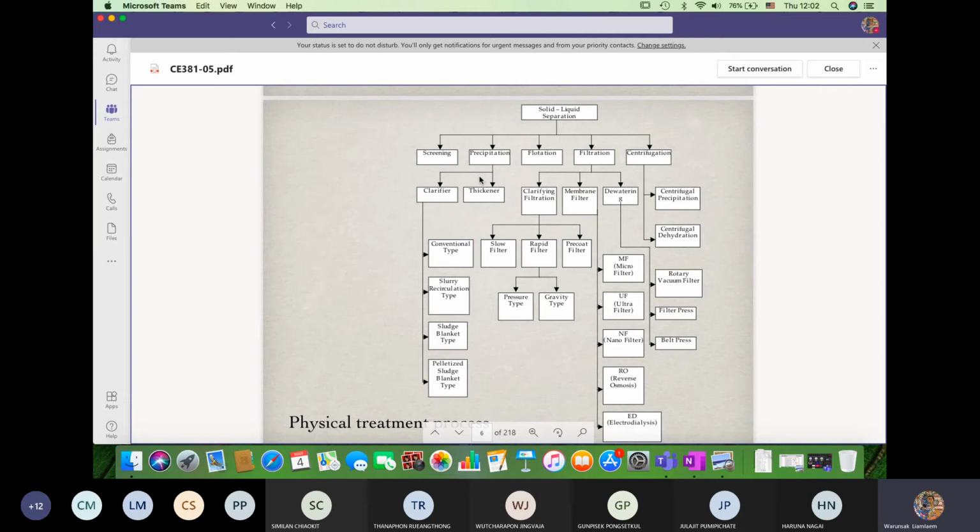So the precipitations, in fact, you can use the sedimentation. Sedimentation would be a better idea in this context because in sedimentation the particles just settle to the bottom of the chamber. But precipitation normally refers to substance A reacted with substance B and then forming precipitated forms. So precipitation refers to the solid matter generated by chemical reactions or probably biochemical reactions. That is why we never use the precipitation in the general point of view. We prefer to use the sedimentation. I mean, I'm talking about this case.